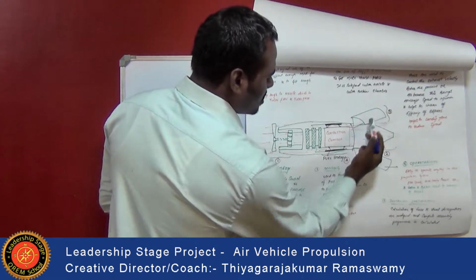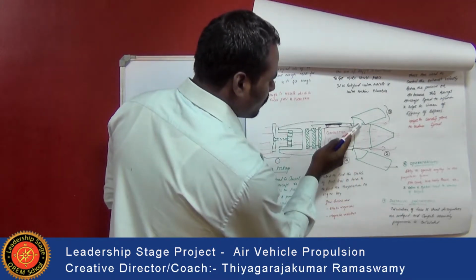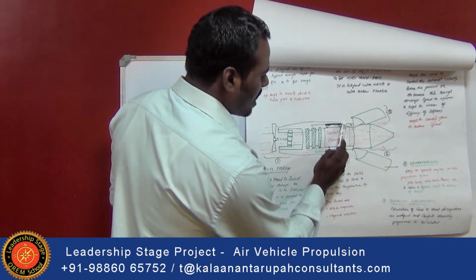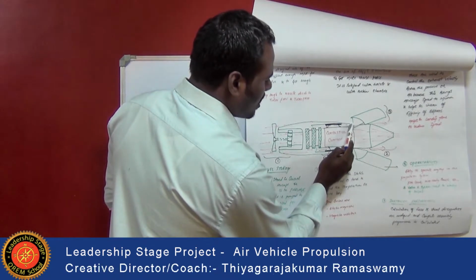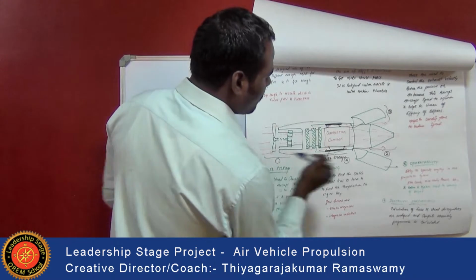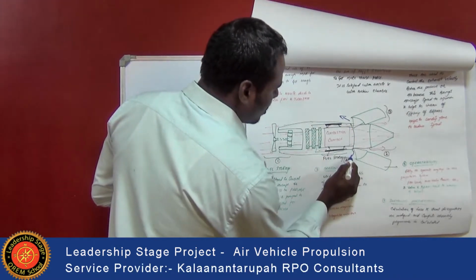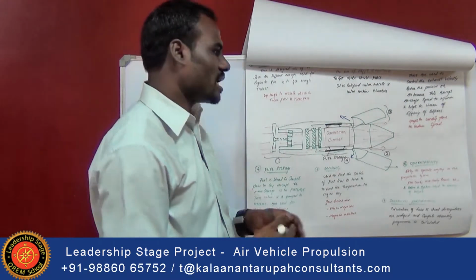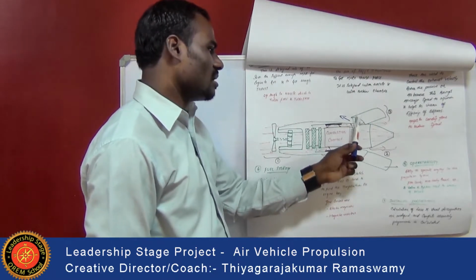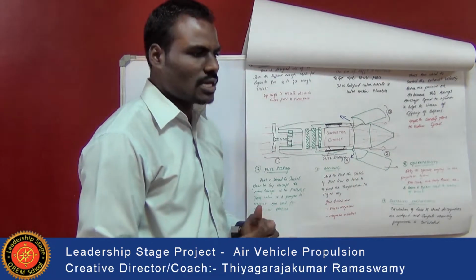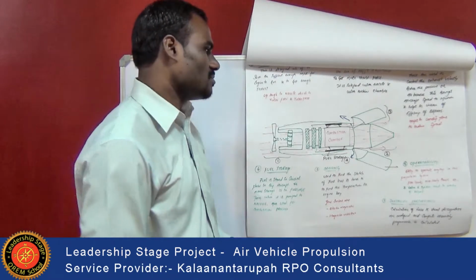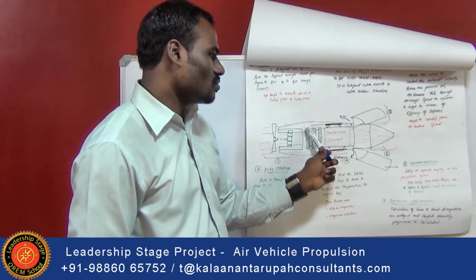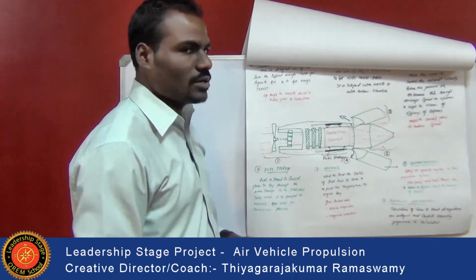Here, the thrust reverser helps us in blocking the air which is coming inside, so that if we open the cowl at the nacelle structure at this area, this helps us in deviating the air which is flowing to the exhaust. The air will be deviated, so that at this area you will be getting the thrust reverser, so that we will be reducing the speed of an aircraft. Here, the thrust reverser is carried out manually, in the sense mechanically, or with a hydraulic or pneumatic system. This thrust reverser structure can be accommodated with respect to the nacelle structure which has already been designed.